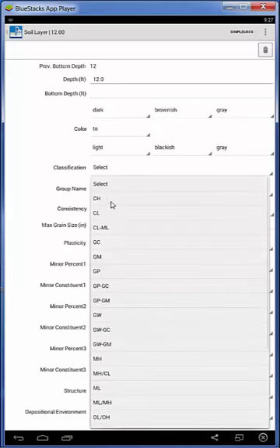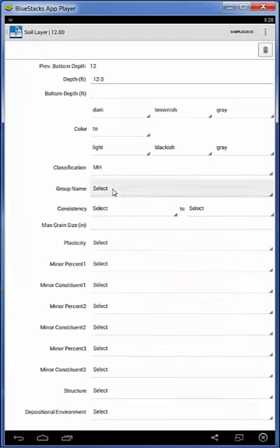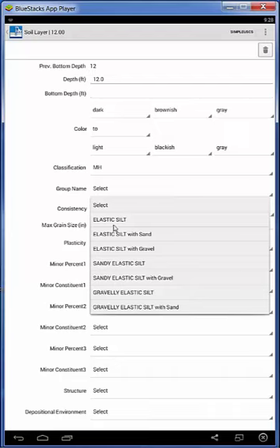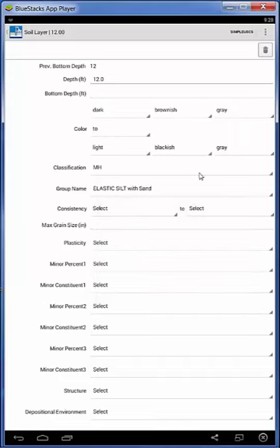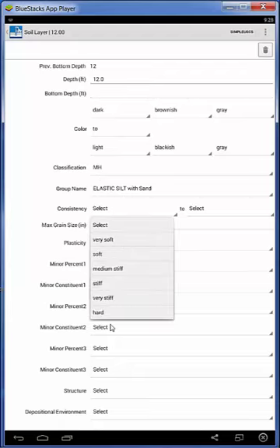In this particular configuration, it's modeling a USCS classification. So let's say I've hit an MH layer, and so I say it's a silt, and because it's an MH, it could be some of these options. So the tablet has filtered the options for relevant soil descriptions. Because it is a fine grained material, it is also going to filter my consistency list as well.